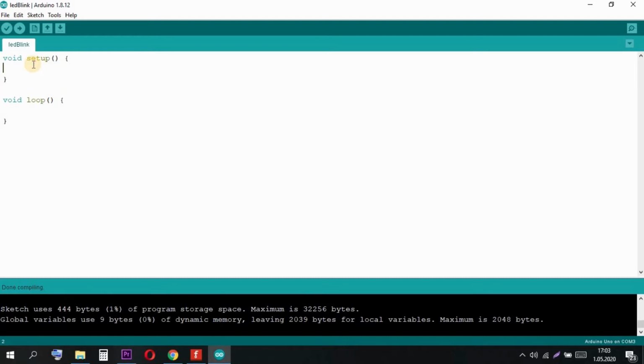So we have a function, a method, for beginning the serial monitor. We just write in the void setup, we just want to begin this serial monitor just once, and we have to write Serial.begin, and in the parentheses we should write the baud rate. Baud rate means how much data in 1 second, I guess. So our baud rate will be 9600, and I will close the parentheses and semicolon. It started the serial communication.